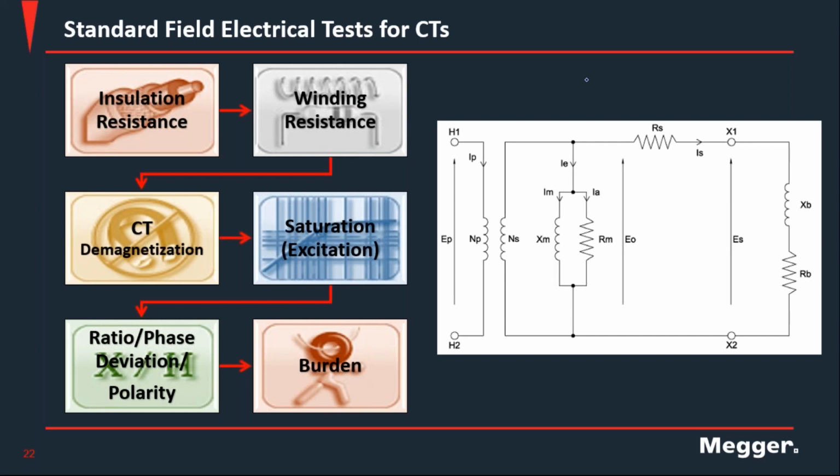The only thing is that, as I talked about in my previous question, you want to run a demagnetization in between or after those DC measurements, to make sure that probable remnant flux in the core does not affect the subsequent test. So if you select your sequence manually, no issues. Just make sure you run a demag after any DC measurement.